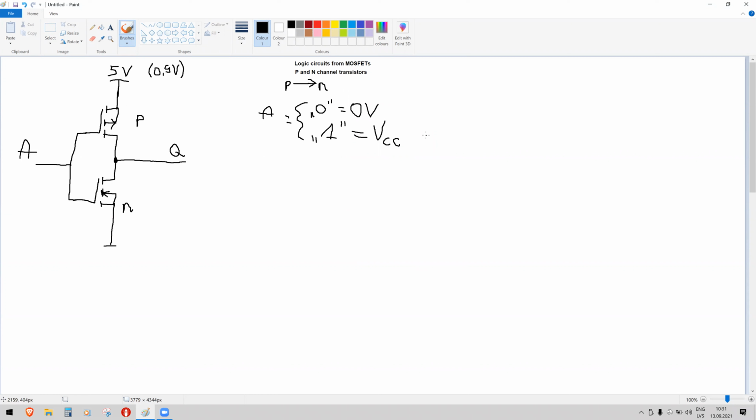VCC, or also VDD, like from drain. Though both of these don't really have any meaning, it's just however people in datasheets tend to write them. VCC or VDD is power supply. In this case, it's, for example, 5 volts in our example. Okay, so I'll delete this one so you don't get confused. Let's say we're using something like a 5-volt microcontroller, for example, Arduino.